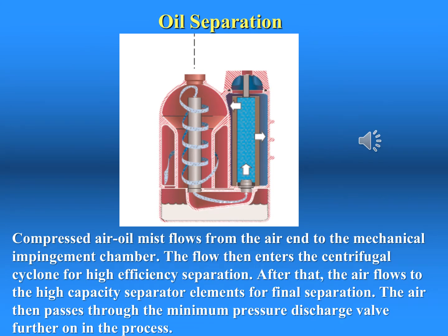Air oil separators work according to the principle of coalescence. Microglass fiber layers separate drops of oil from the compressed air and return them in large drops to the oil circuit of the compressor. The separation process is effective enough to reduce particle size to the sub-micron range, particles less than a micron in size. This ensures that oil consumption in the compressor and oil entrainment into the compressed air network are kept to a minimum. Oil vapor is not separated.